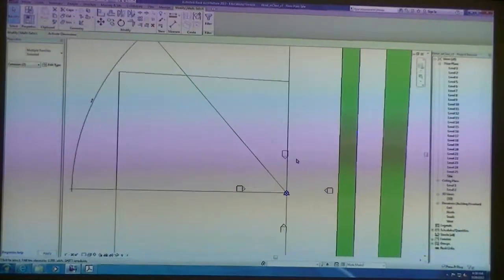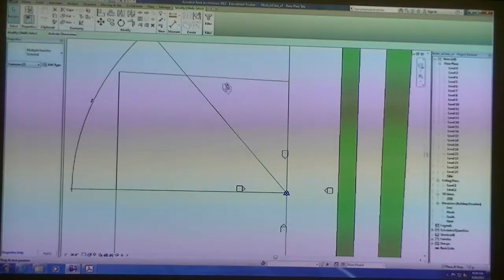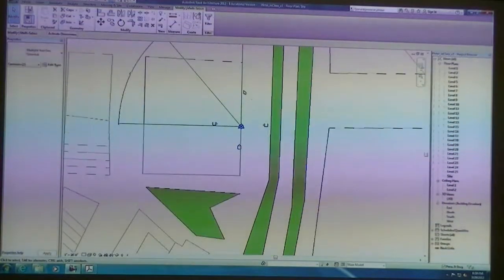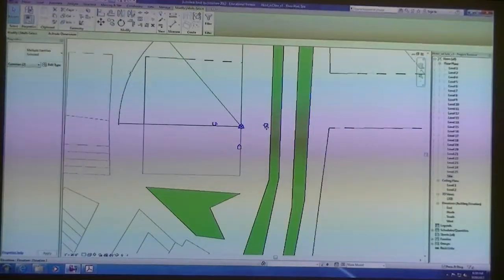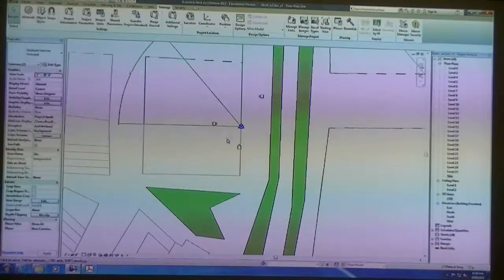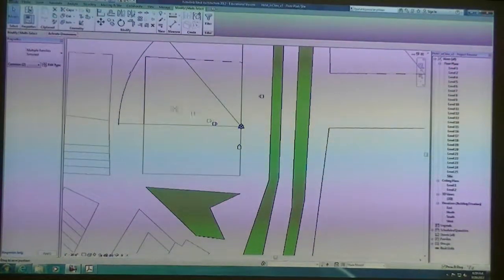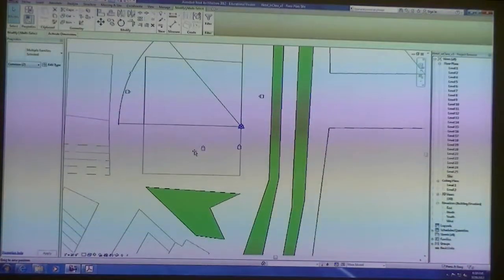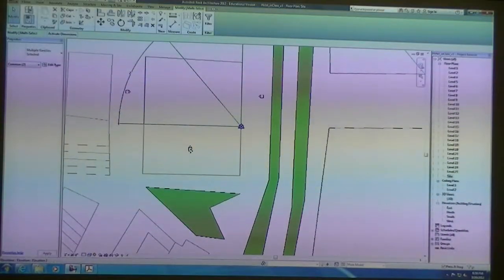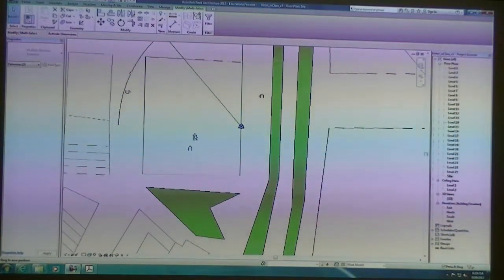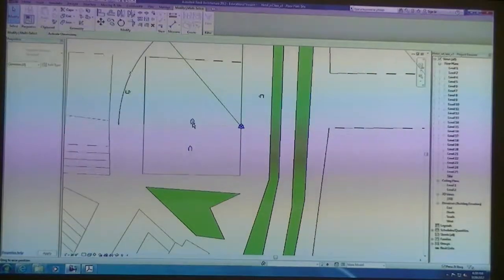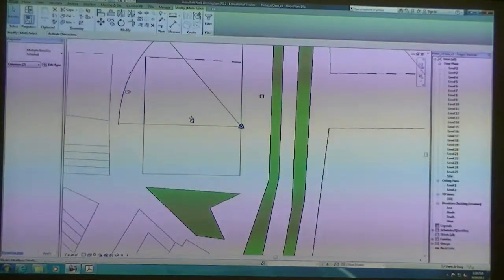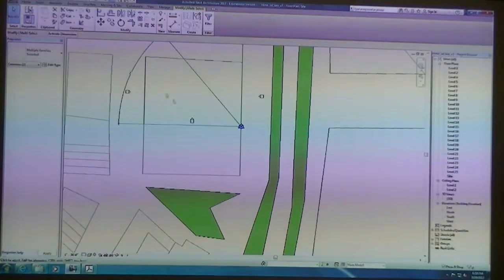So I'm going to take my north, and I'm just going to move and drag it to the north of my site. I'll do the same thing with the east. I'll just kind of center them as best I can, eyeballing it, so that when we actually take an elevation view, we will see our site. And I'll probably move this elevation tag so that it's not in the building, and it's just a little bit north of our boundary line.